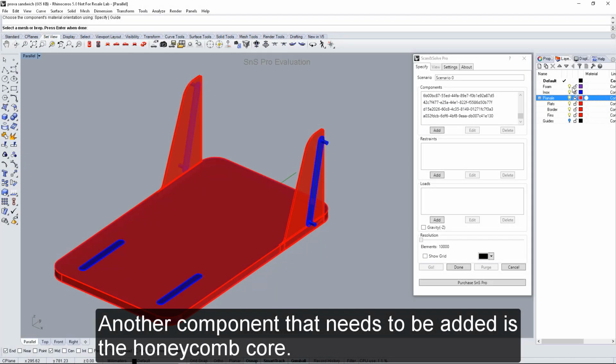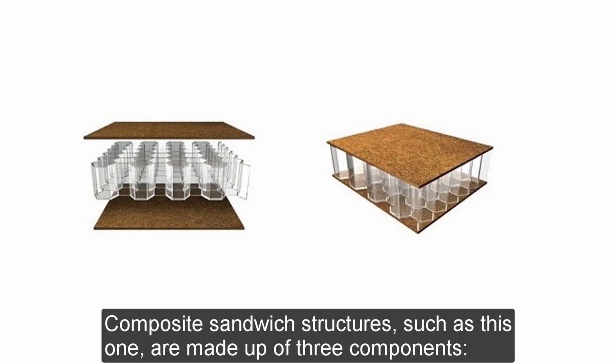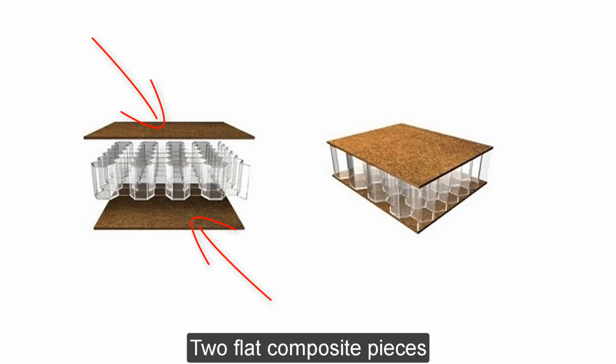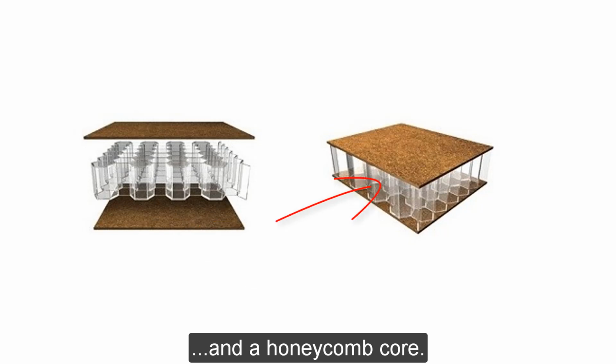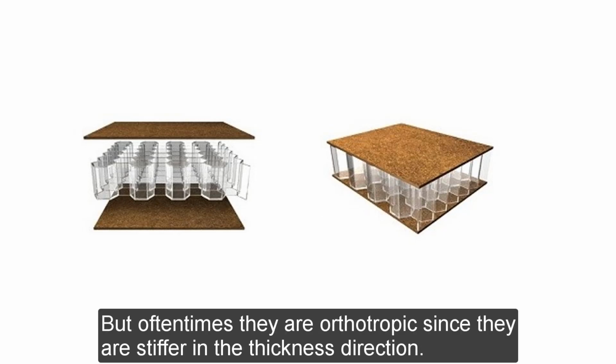Another component that needs to be added is the honeycomb core. Composite sandwich structures, such as this one, are made up of 3 components: 2 flat composite pieces and a honeycomb core. Sometimes the honeycomb core has similar material properties in each direction and can be modeled using an isotropic material, but oftentimes they are orthotropic since they are stiffer in the thickness direction.